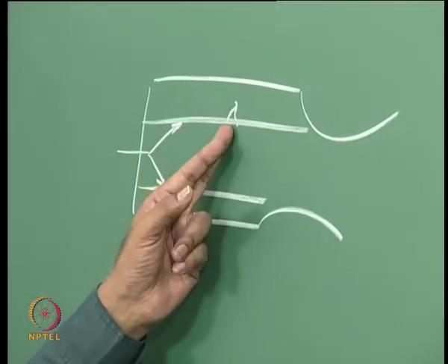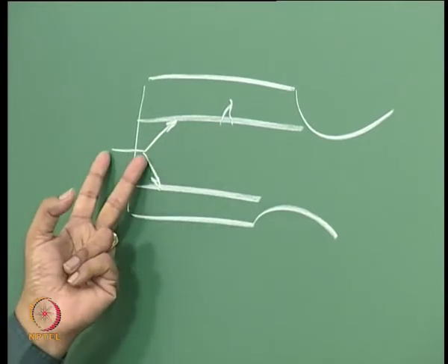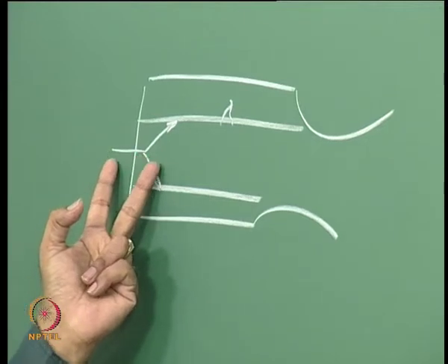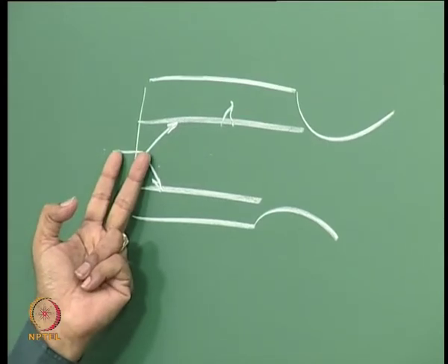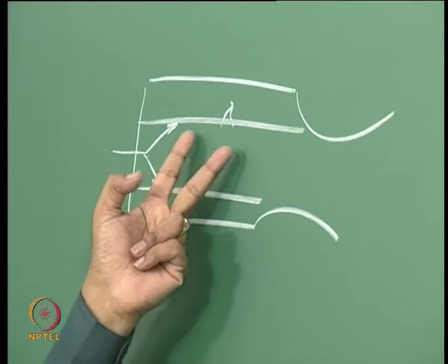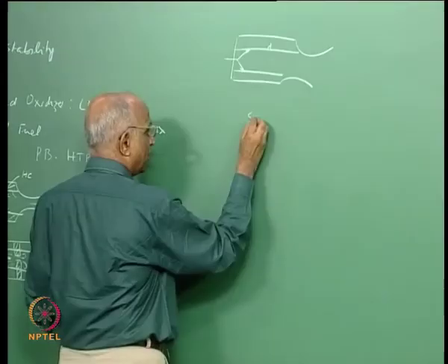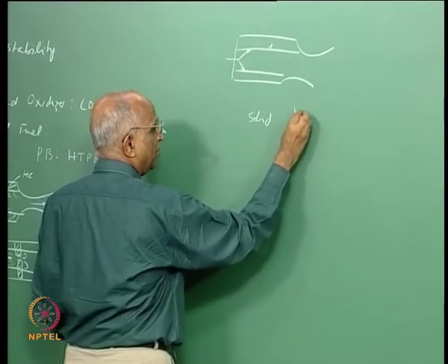Because the surface area is increasing, pressure gets generated. When pressure gets generated, automatically the pressure drop across the injector decreases, because the pressure here is higher and this is constant pressure. The pressure drop decreases, and therefore the flow rate of oxidizer decreases, and therefore it is self regulating. In other words, in solid propellant rockets, if there is a crack, its surface area increases and pressure continues to increase.